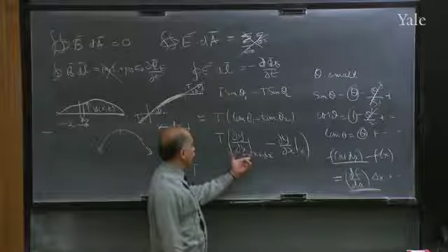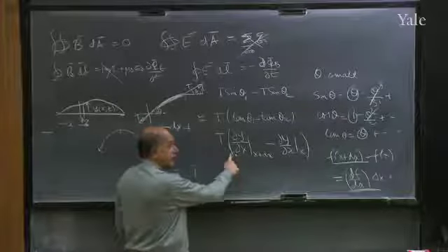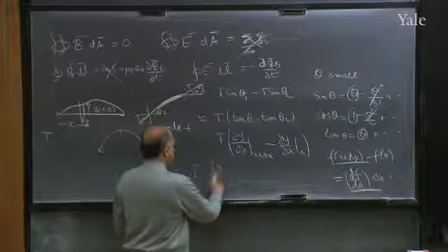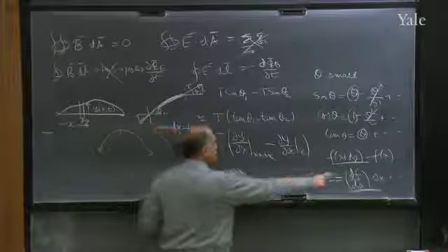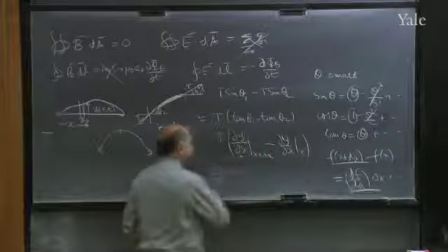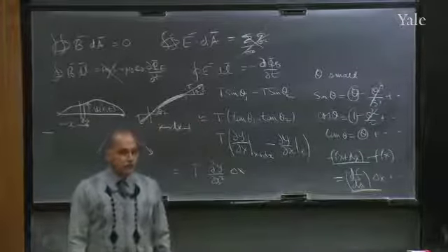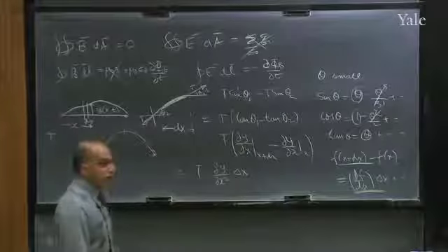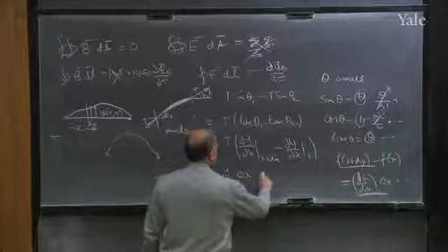So this slope changes from here to there. Therefore, it's the derivative of something which is already a derivative. So it's d²y/dx² times delta x. In other words, the f I'm using here is itself dy/dx. The df/dx is then the second derivative. So that's the force. Now that force we must equate to ma.